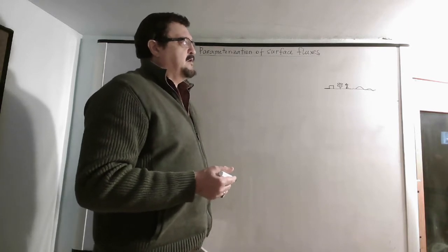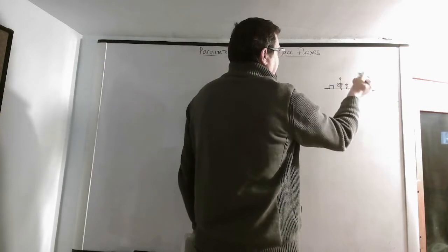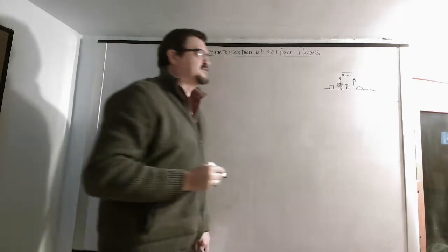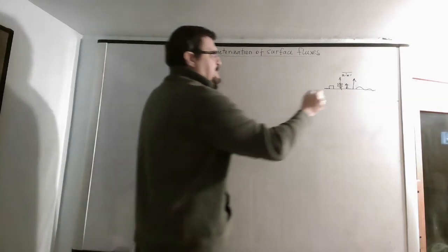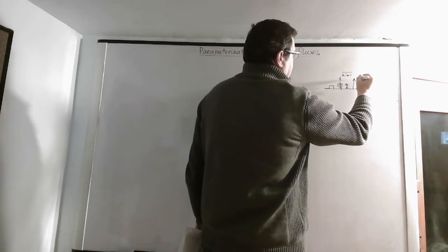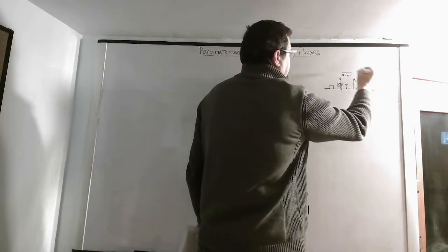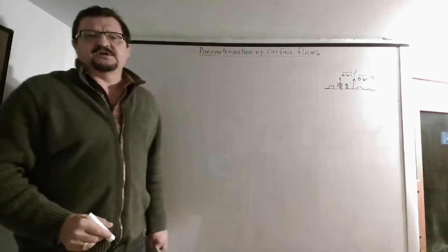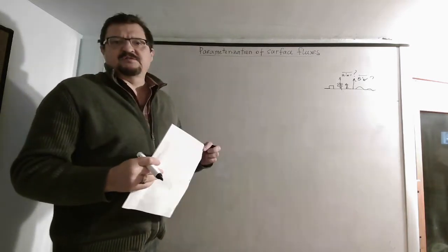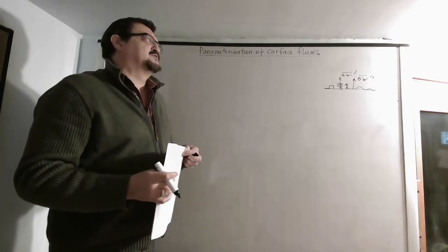So, how do you parameterize all these fluxes of momentum, like u prime w prime, these Reynolds stresses at the surface, or fluxes, say, of potential temperature or heat fluxes at the surface? So how do you parameterize them? And for that, we will use the so-called Monin-Obukhov similarity theory, which is kind of standard for this kind of problem in our field.